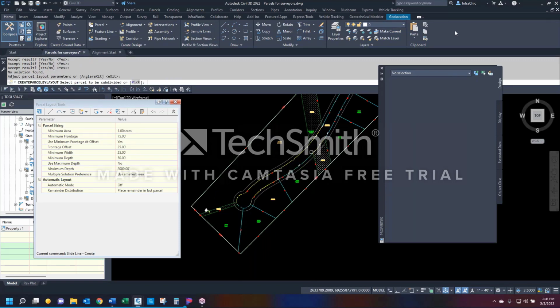Last one. Now, this is the one I've had a little problem with in the past, so it may be a little weird, but we're going to give it a shot either way. Select the label, come over here to the drainage easement again, say end, and go to the pipeline easement, end. Yes, enter, yep, beginning and end looks good. Enter, enter, enter, enter. This is the one that's weird.